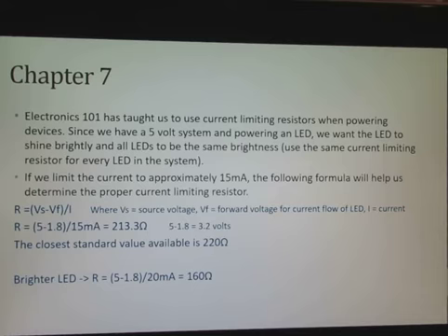So we always use resistors with the LEDs, but do we actually determine the value through some kind of scientific effort? Sometimes we don't. It all depends on the amount of current we want to allow to flow through the device. This will affect the brightness. Let's go through this example.